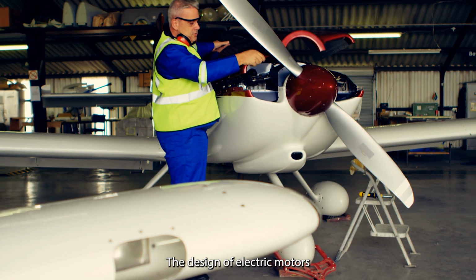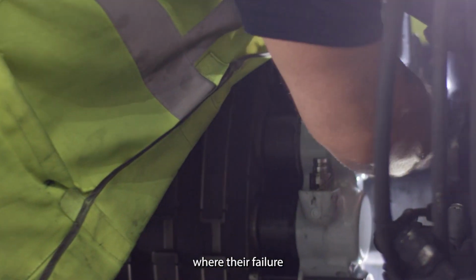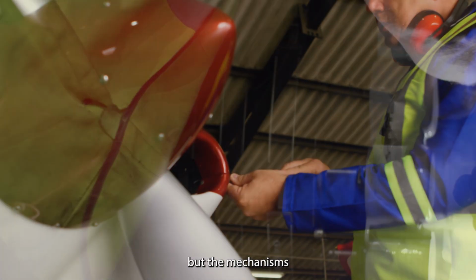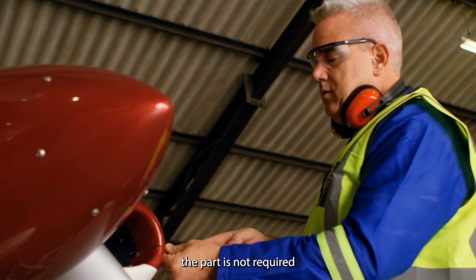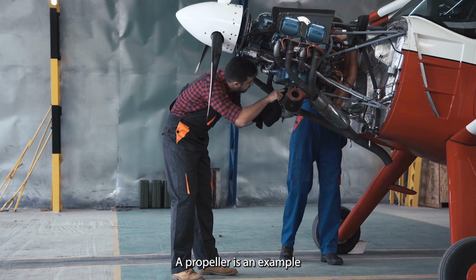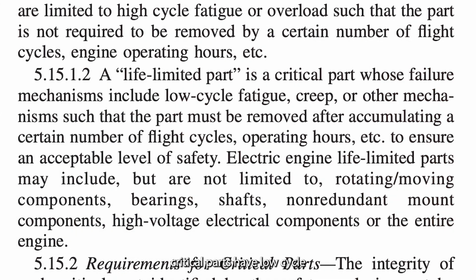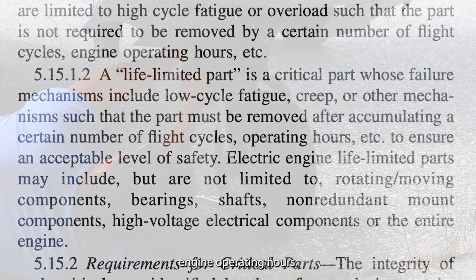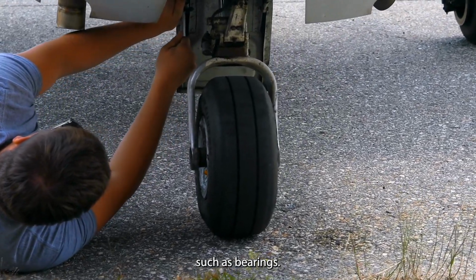The design of electric motors includes how to handle life-limited and critical parts. Critical parts are those parts where their failure could cause a hazardous effect, but the mechanisms are limited to high cycle fatigue or overload. As such, the part is not required to be removed after a certain number of flight cycles or engine operating hours. A propeller is an example of a critical part. Whereas life-limited critical parts have low cycle fatigue, creep, or other mechanisms and must be removed after accumulating a certain number of flight cycles or engine operating hours. These parts may be forced to be replaced during scheduled overhaul, such as bearings.